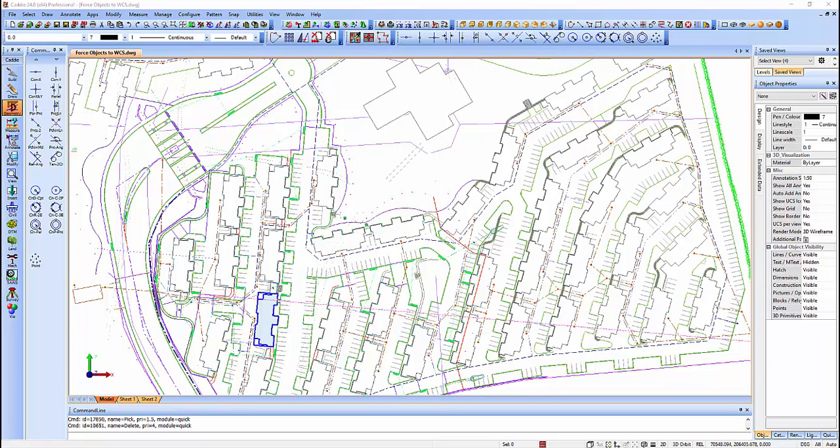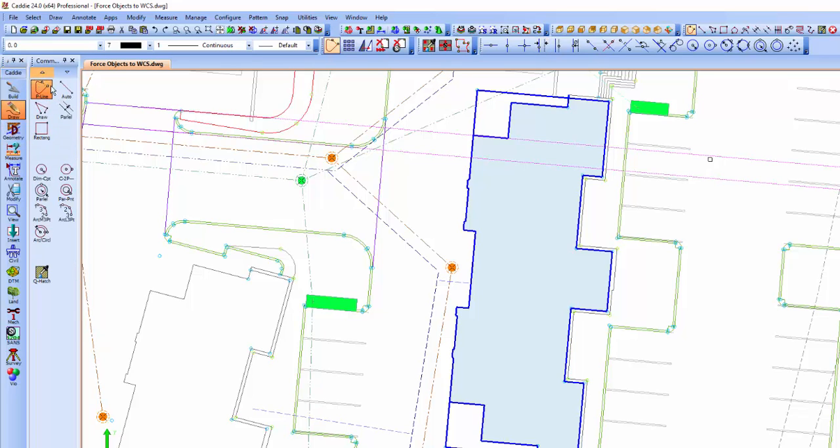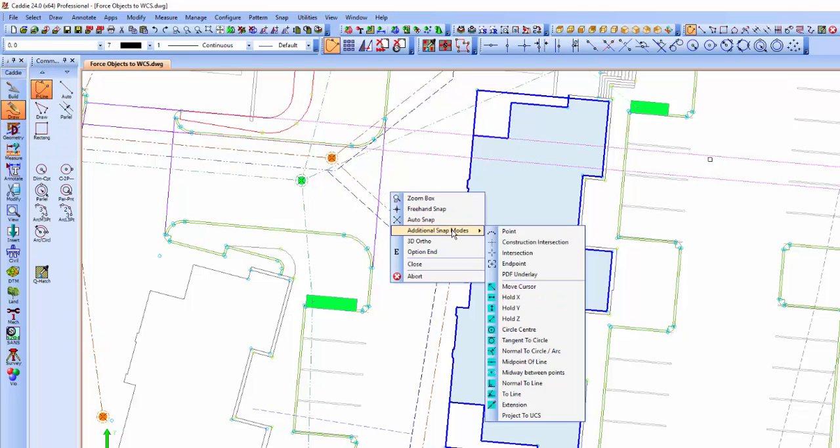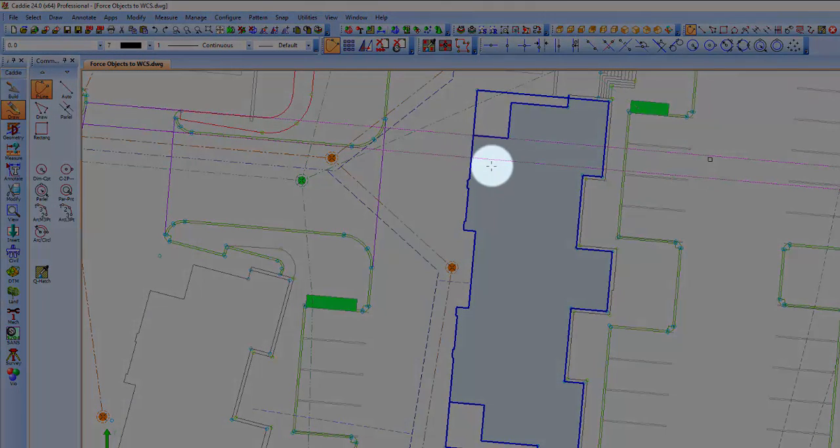However, looking at our drawing, and we'll just take a closer look here, we may be wanting to set something out with geometry lines, construction lines. So here I'm just going to do a parallel offset of 1800 millimeters, giving us what would appear to be an intersection. Choose our polyline command, choose our intersection snap mode, and we see that we don't in actual fact have that intersection noted, whereas moving around our drawing we can see the intersections are being picked up elsewhere.